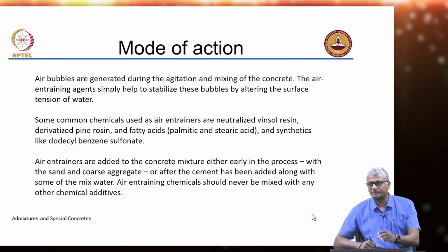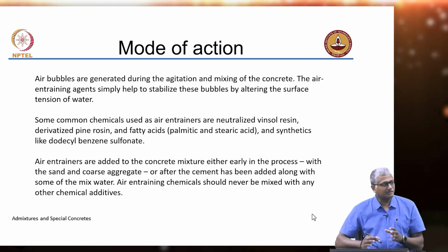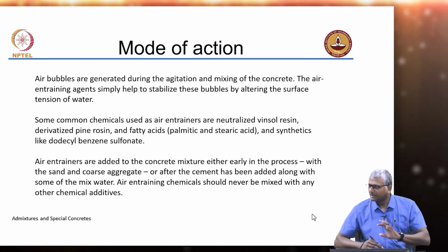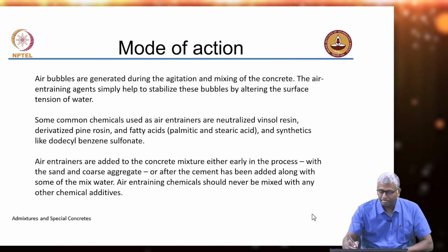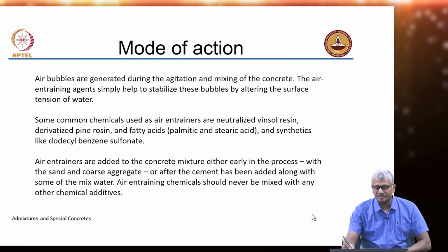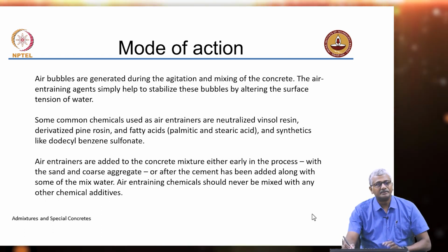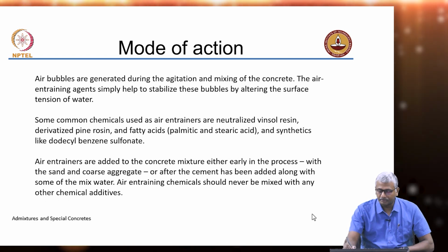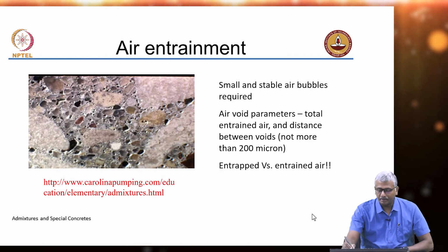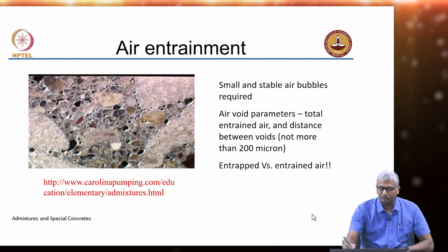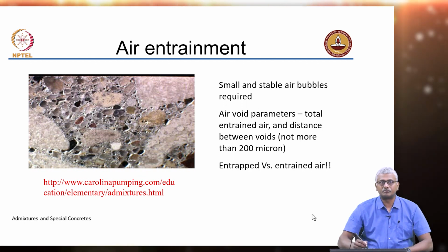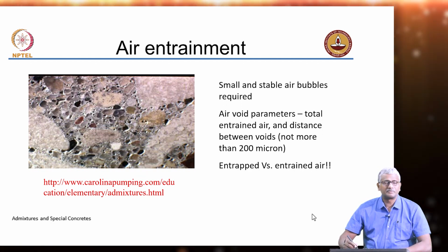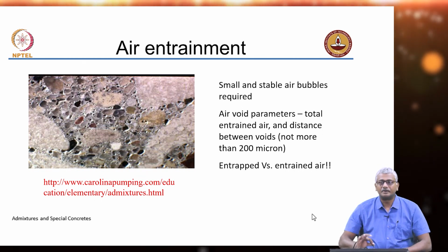We will talk about different types of cement, but in all cements, if you combine C3S and C2S together, it will be more or less close to 80%. Again, C3A plus C4AF together will be about 12 to 15%, and gypsum is around 3 to 4%. That is the amount of gypsum that is available in the mix.